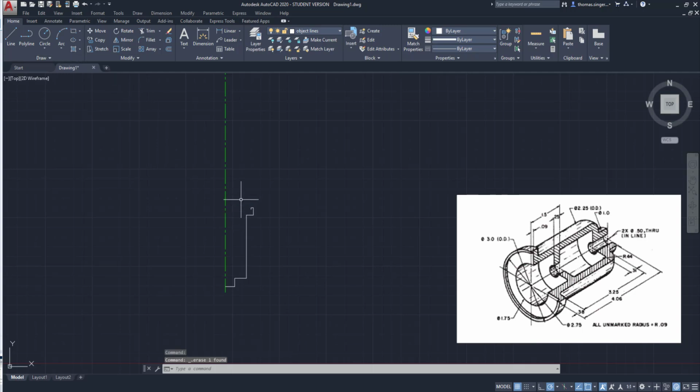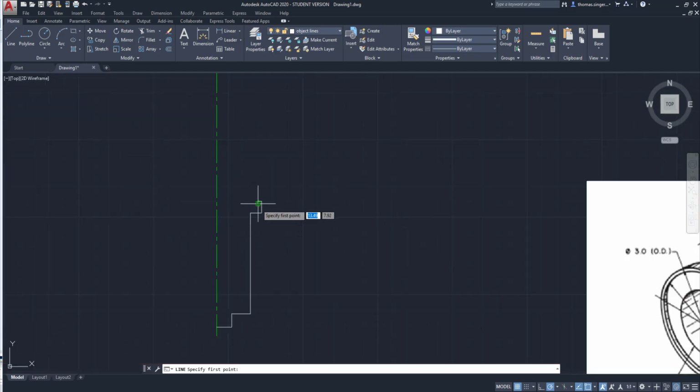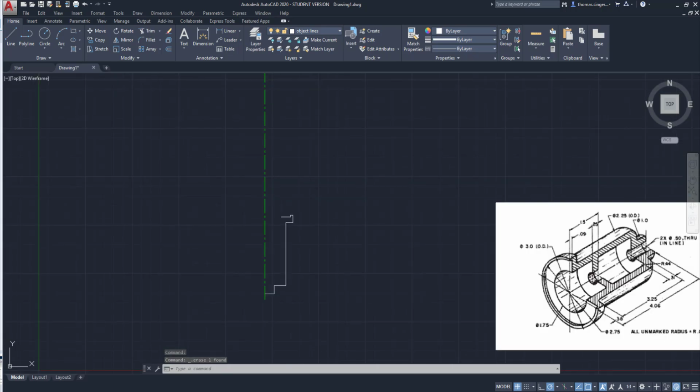So let's go ahead and erase that. Draw a line. Let's magnify, highlight this to bring it straight over to find the intersection point. Bring this out and 0.875. Hit the enter key and then connect the last dot to the end point there and erase the original 0.875 line. So that is now the opening surface there. So now we have to create the interior shape.